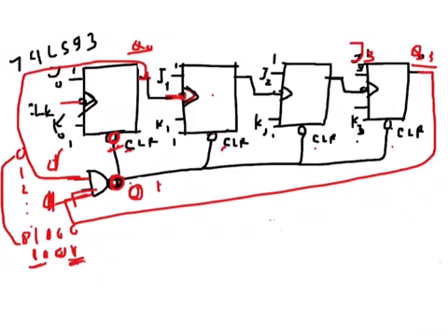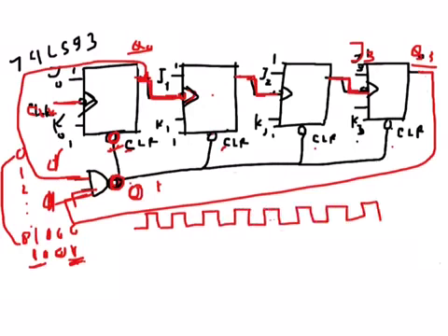So that's understood. Now I will connect this one as an up counter, so it will be an asynchronous one. This is the main clock here, and this output will be connected here, and we will see that it will act as an ordinary up counter. If this is the clock, the clock goes like that, and it's a falling edge, so it will work on the falling edges.